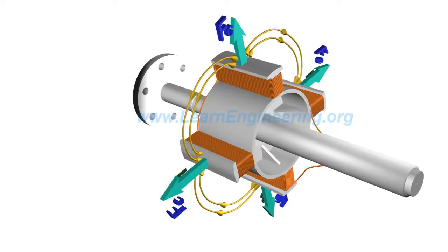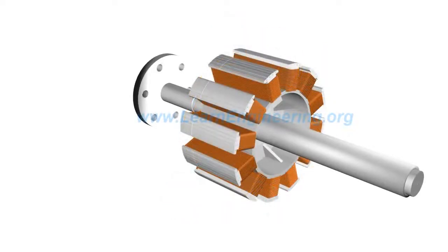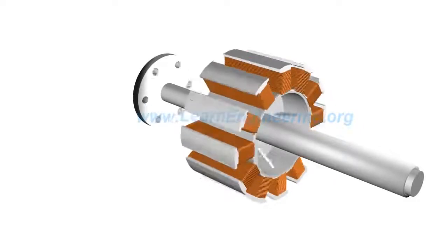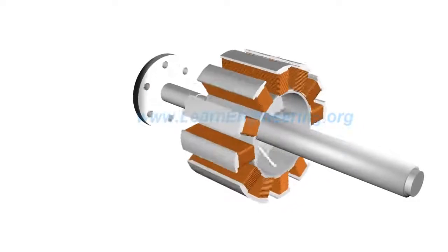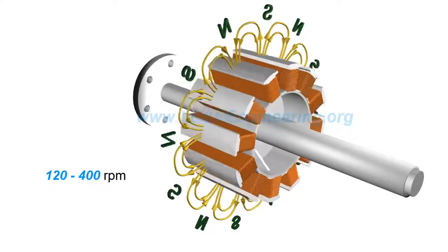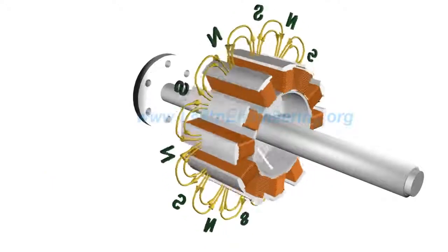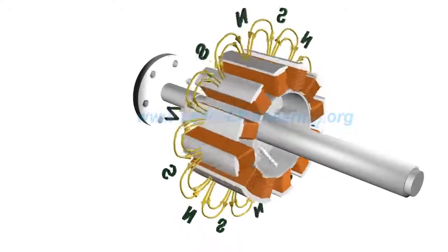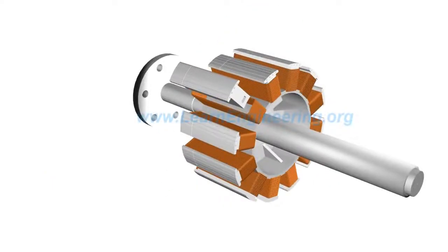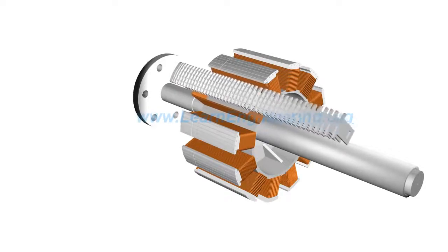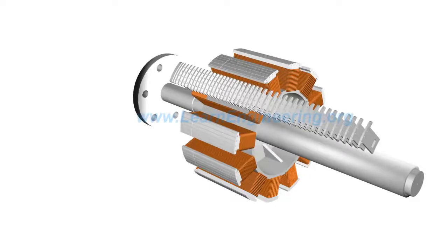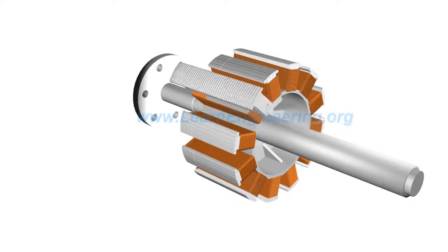So salient pole rotors generally have 10 to 20 poles, which demands lower RPM. Or, salient pole rotors are used when the prime mover rotates at relatively lower RPM. Pole core is used to effectively transfer magnetic flux, and it is made with fairly thick steel lamina. Such insulated lamina reduces energy loss due to eddy current formation.